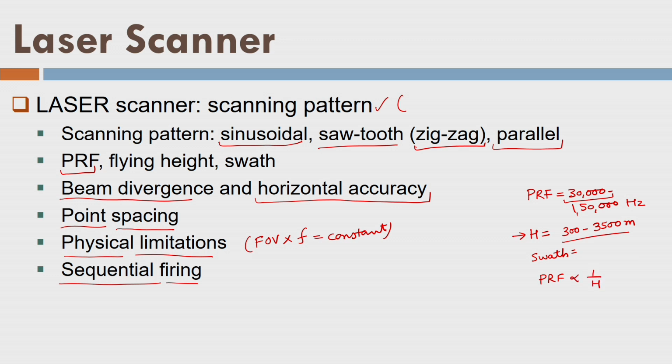There is one more reason for that, and we have discussed it in the last lecture also. Since we need more power if I want to measure a larger distance, each and every pulse should have more power so that once it travels through the space and comes back to the receiver, it will have enough energy reflected from the object surface. As a result, if I have limited power, then I can fire a limited number of pulses.